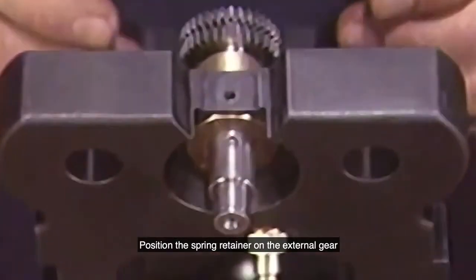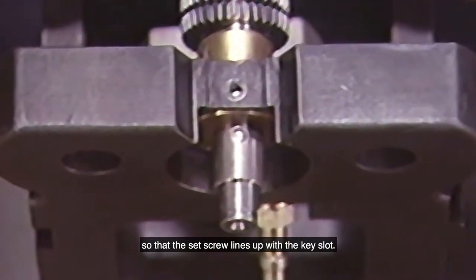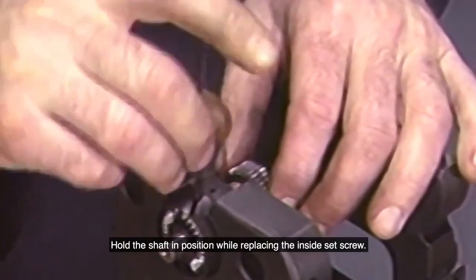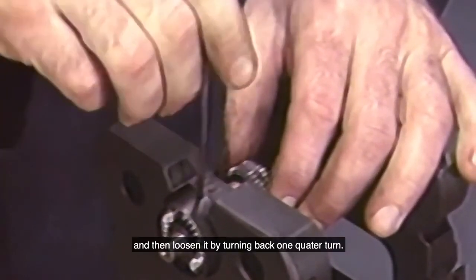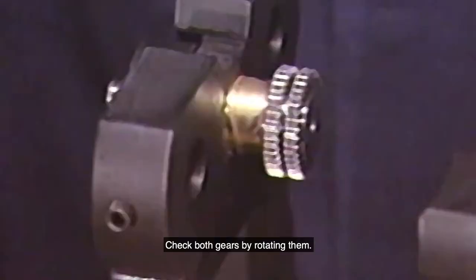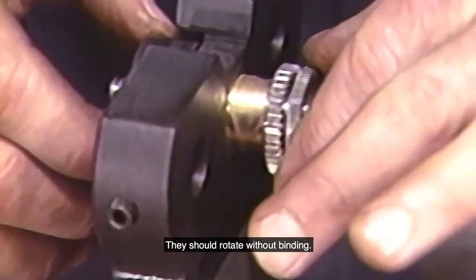Position the spring retainer on the external gear so that the set screw lines up with the key slot. Hold the shaft in position while replacing the inside set screw. Turn the set screw all the way down and then loosen it by turning back 1/4 turn. Now replace the outside set screw. Check both gears by rotating them. They should rotate without binding.